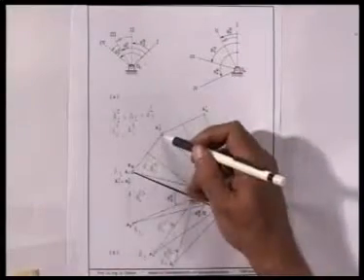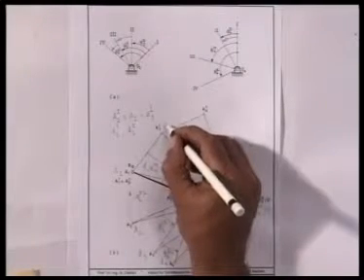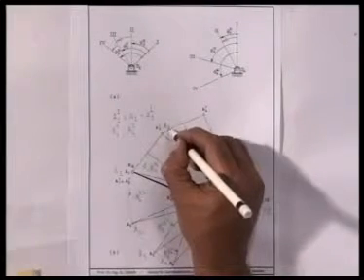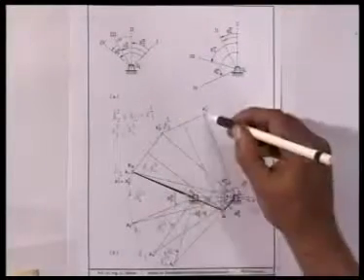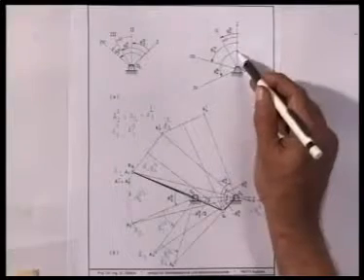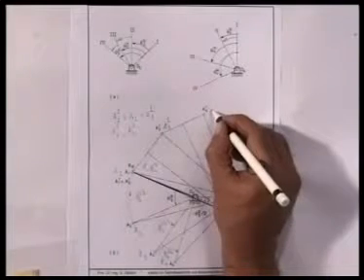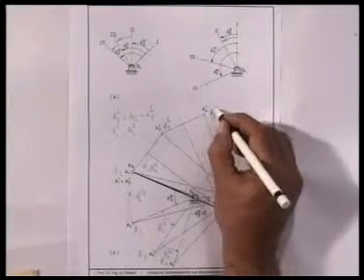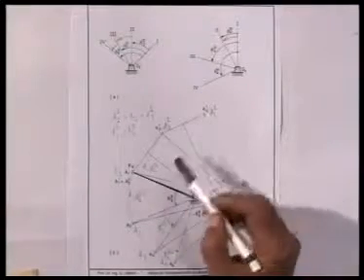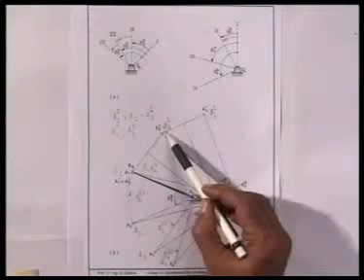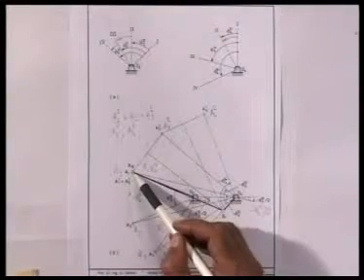So, I rotate it clockwise because it is minus theta 4 1 3, and I get what I call A31. Then rotating O4 A4 through minus theta 4 1 4. This is counterclockwise. I rotate it clockwise and get the inverted position of A4 as A41. So, you see, for the 4 inverted positions, I have only 3 distinct locations. This is A31, this is A41, but A21 and A11 are coincident.